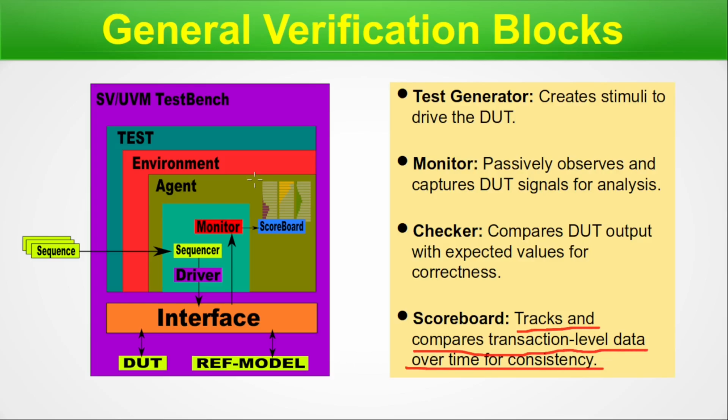That means we give a huge robust verification routine, right? And that creates multiple kinds of variation and injects them into the DUT, and the output comes to the monitor, and the scoreboard will have a mapping level data mining for the verification input and the corresponding output from the DUT. And this scoreboard will be checked in detail to verify whether the design has failed or not. That means we have all the data there.